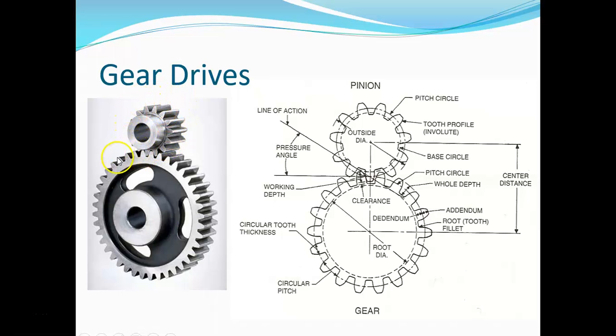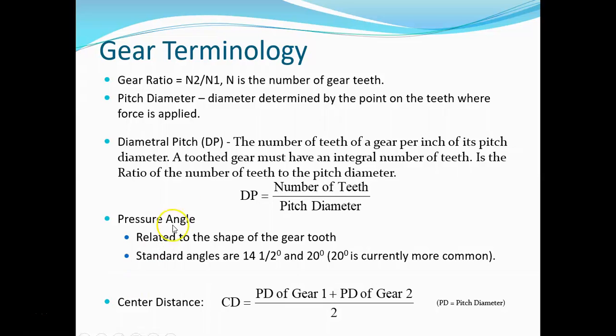And just for easy math, we'll say the bigger gear has 50 teeth. What we're going to do is divide the number of teeth on your smaller gear into the number of teeth in your larger gear. So our smaller gear is 25 and our larger gear is 50, and that's a division of 2. So we're going to express that as 2 to 1.